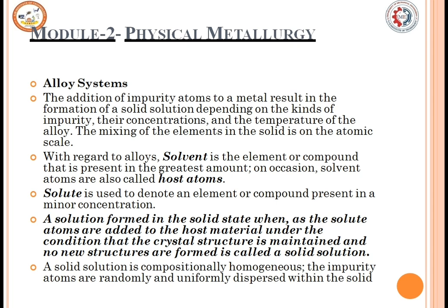So then what is a solution? A solution is formed in the solid state when solute atoms are added to the host material under the condition that the crystal structure is maintained and no new structures are formed. This is called a solid solution. So like this, when we go with phase transformation, you must be able to distinguish between solution, solute, and solvent.